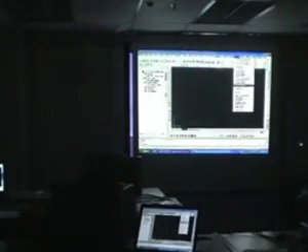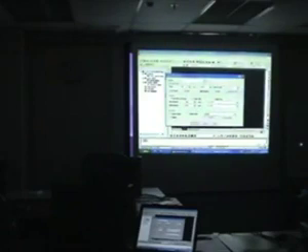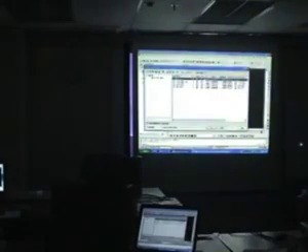Okay, I'm going to create contours. You can see the values have been inserted for me automatically as well. Elevation range from this level to this level automatically for me. You can set intervals at minor and major, minor only, or major only. I'm just going to click OK. Yes. You can see the contours have also been automatically created for me. Again, these have also been created on their own layers.